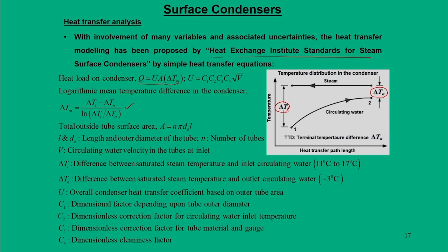Now, what is not known to us is U. This U is a function of various parameters, and the Heat Exchange Institute standard says that the overall heat transfer coefficient can depend on various factors. The first factor is the outer diameter. The second factor is the circulating water inlet temperature.